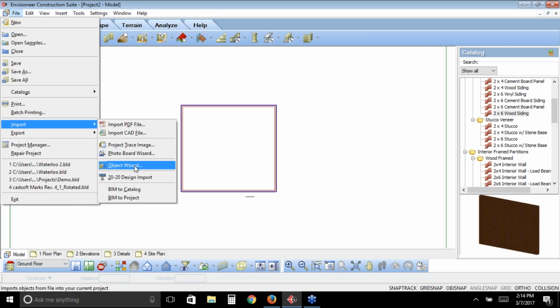The other object types that you can bring in are actual 3D objects. And when we bring in the 3D object, it can be a SketchUp file, it can be an AutoCAD file, it can be a 3D Studio file, or a DXF file. And these are, again, 3D objects. So we can bring in the DWG files in 2 different formats, a flat 2D CAD file in DWG or DXF, meant to trace over, or an actual 3D object that we want to use in our model.